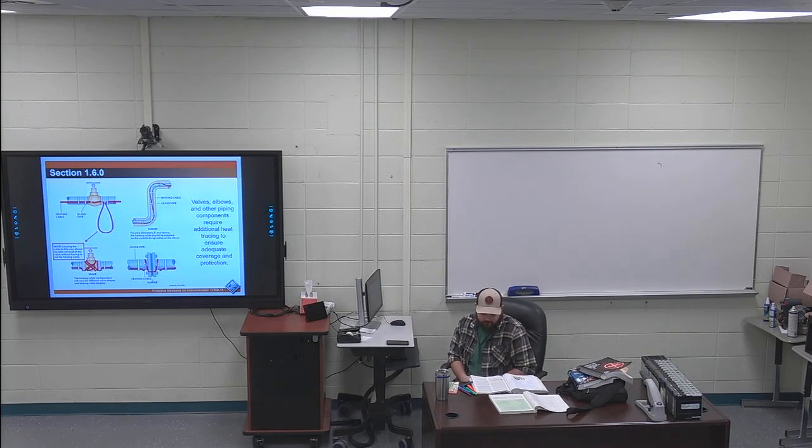The highlight that I have on page 13 for 160 is on the right hand side of the page. That second bullet point in the top right, second to last sentence. Typically 2 feet of cable is added for each electrical power connection, splice, T, and end seal. So it's just extra cabling, because a lot of this stuff you can cut to length and splice, but that's extra cabling for those purposes.